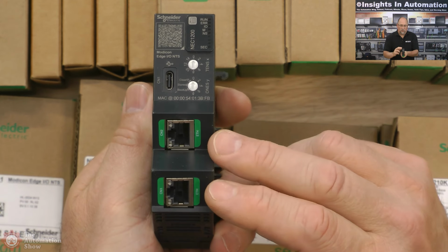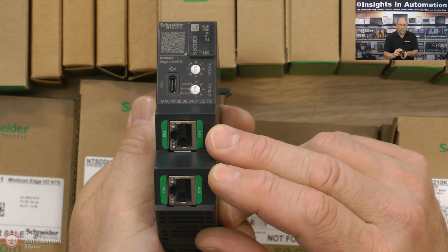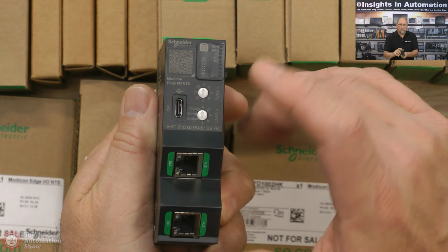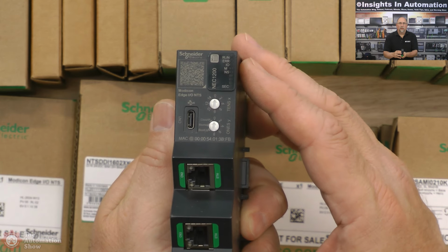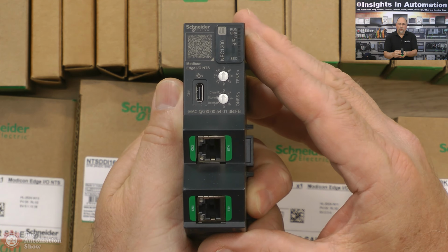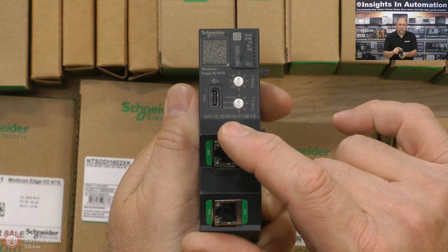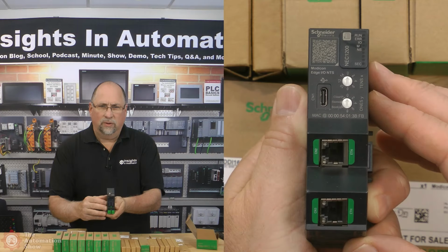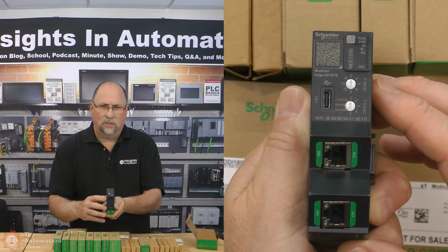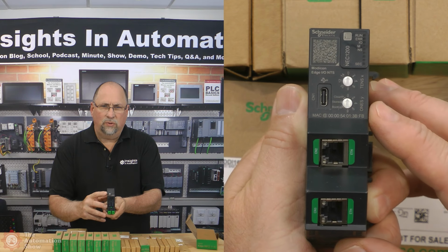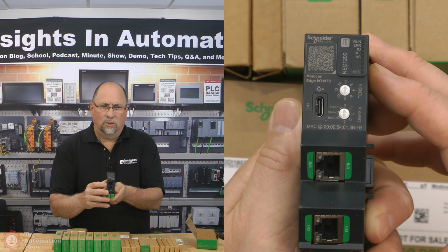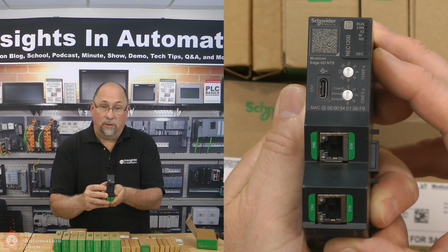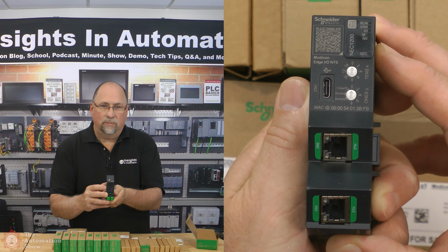So to start, we have this 2-port switch, Modbus TCP and Ethernet IP, which is so awesome, having both protocols. We also have a USB-C, so maybe you don't know what the IP address is. You can plug in that way and configure it. We also have the MAC address right here on the front, very easy to find, and that's very important. We'll see more about that later. We also have the 1s and 10s for the name, and then you'll notice on that switch there, you'll see an option to clear the IP, to use the stored IP, or to use BootP.